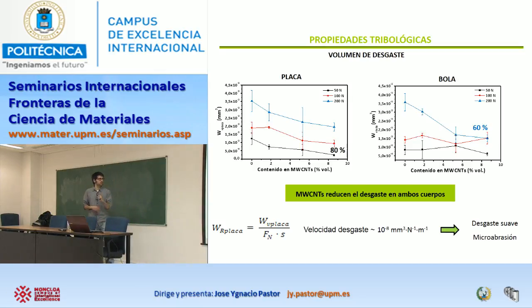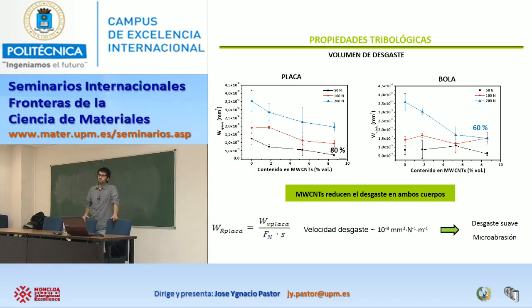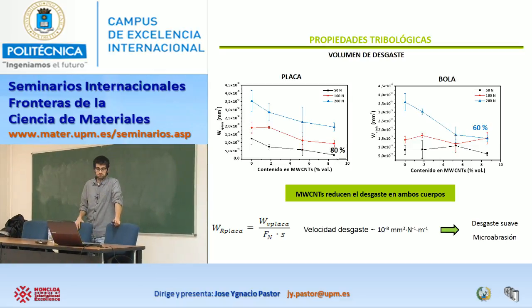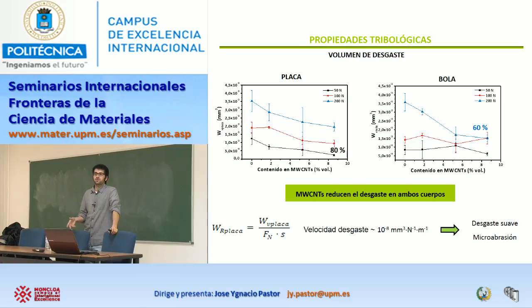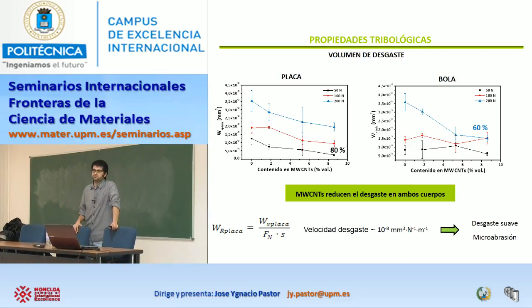One important thing is that nanotubes, as I show you, look like they are quite easy to disperse, but nanotubes are really complicated. We had a problem: we bought these nanotubes from a commercial company, perfect, and the dispersion was great and easy. We asked the same company again, and when they brought other nanotubes, we could not disperse them. It changed from batch to batch, and it's really complex. We tried with other companies, and we always observe bundles of nanotubes.